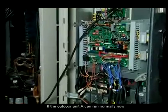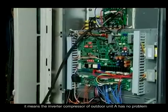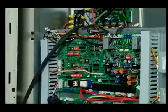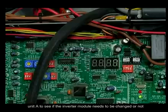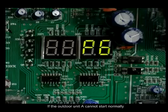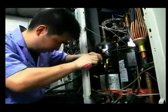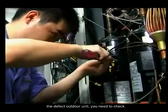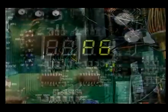If the outdoor Unit A can run normally now, it means the inverter compressor of outdoor Unit A has no problem, but the electronic control probably has a malfunction. Now, you need to check the electronic control of outdoor Unit A to see if the inverter module needs to be changed or not. If the outdoor Unit A cannot start normally, that means the compressor has a malfunction and needs to be changed. If there is no other outdoor unit of the same series near the defective outdoor unit, you need to check and repair as follows before changing the compressor.